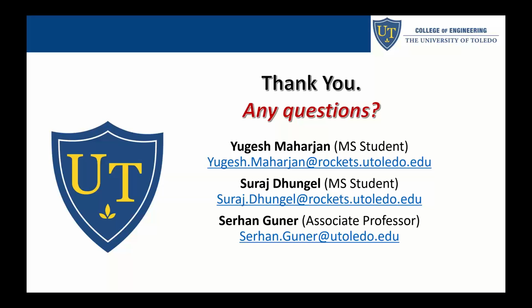Great. We do have some additional questions for you. This one I'm going to read came in right after the second part started, so it may be related to the first part. It says, what about shear check ODOT requires for box beams? Shear check is done according to what ODOT BDM requires. We developed this tool for ODOT, so definitely we are following their requirements. We are also going one step further to do additional checks at every shear reinforcement change location.